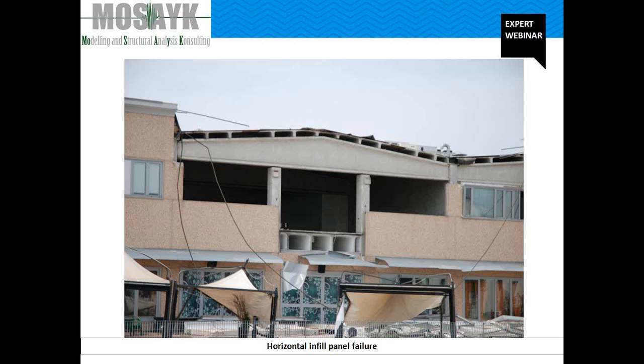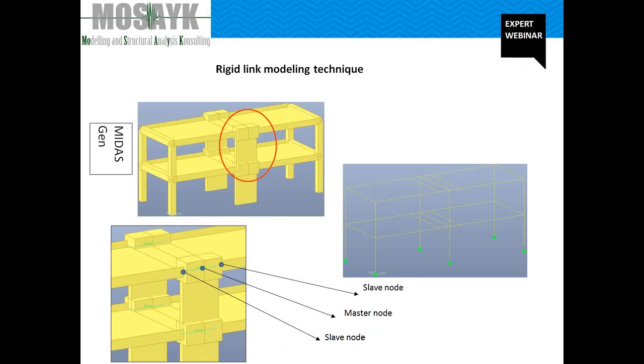During an earthquake, this kind of connection needs to accommodate high relative displacement and rotation because the displacement and rotation demand are concentrated at the connection level, owing to its lower stiffness compared to connected precast elements.